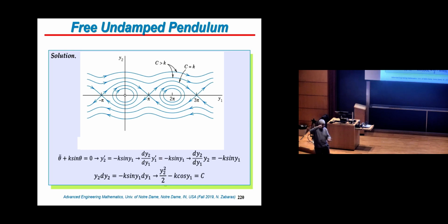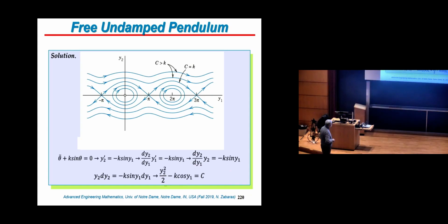As the pendulum oscillates, if you take the bottom to have 0 potential energy, then at a given location the height will be L times 1 minus cosine of theta. So the minus cosine of theta gives you this term. The other term is constant, and it's incorporated in what I indicate here as C.